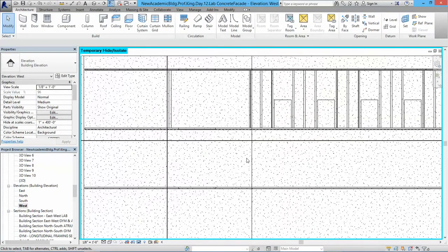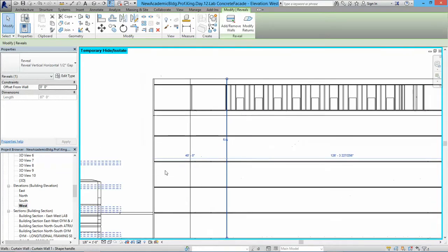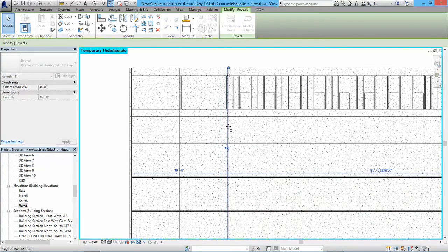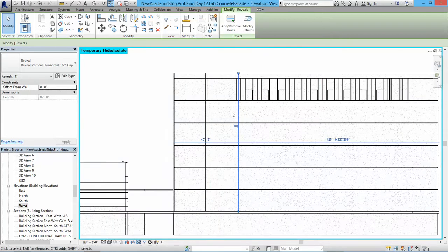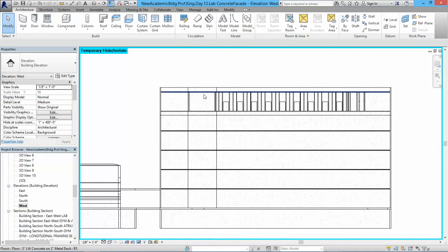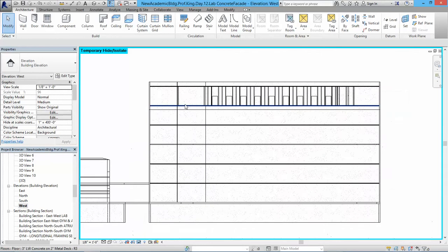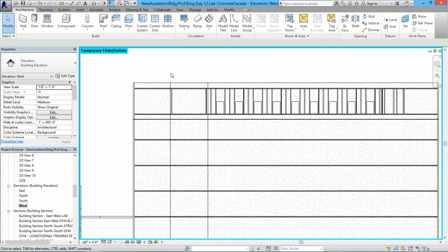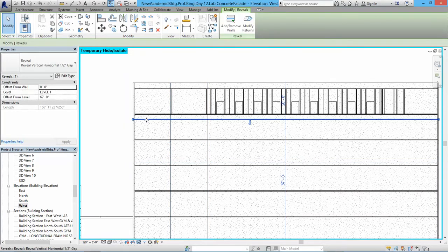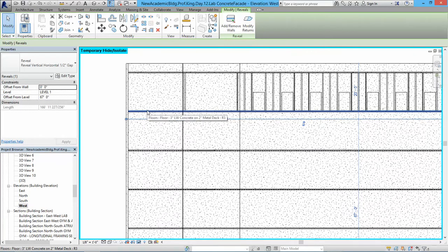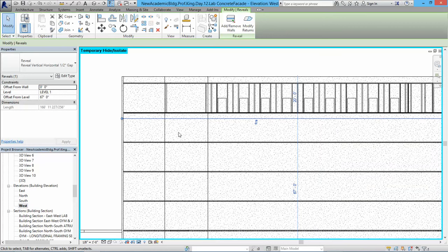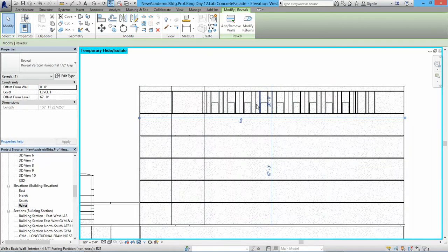So basically what I'm trying to do is that you can play with your reveals from the west elevation, move it around more in relation to the walls. You could keep the stairs here so you see exactly where that's going. You don't necessarily need the stair unless they're affecting the windows, which it makes sense most of the times, but you can be free of moving your reveals both horizontally and vertically in relation to the floors. You could have the structure. It's very, very convenient to work in an elevation, so you have control of what's happening behind.